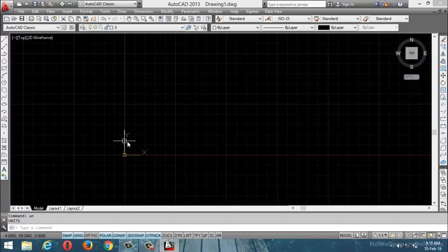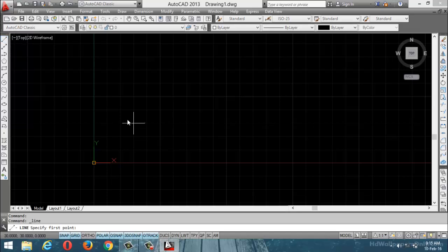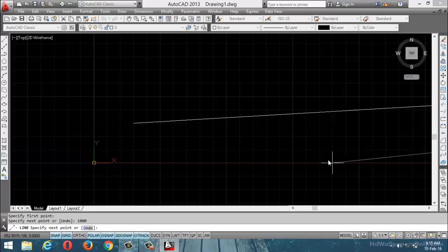Then see here. Now I am going to design one line here. My length of the line equal to 1000. What happened here currently? Not displayed. Again see here, the design is going outside of the drawing window. For that purpose, first you can assign the limits of the drawing. For that purpose, you can enter the command, limits. Just wait.